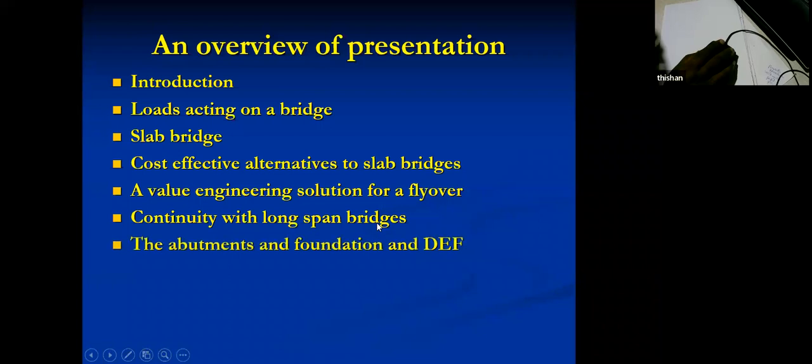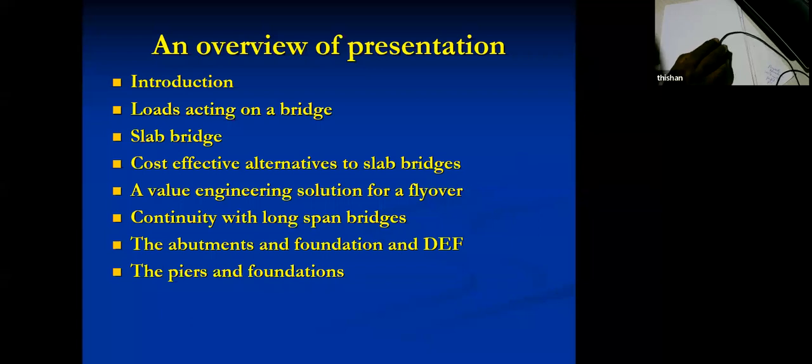And then how we deal with abutments and foundations. Also, one of the key problems we encountered in many of the southern highway bridges up to Matara was called DEF, delayed ettringite formation. So we can talk about that problem also, just to get some overall idea. Later I can tell you a lot more about it and how to avoid DEF, and if time permits, we can come back to that topic today itself.